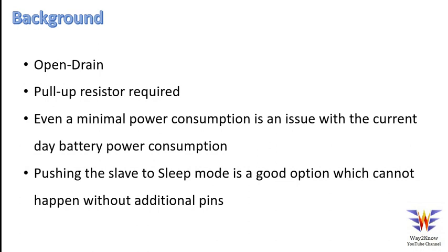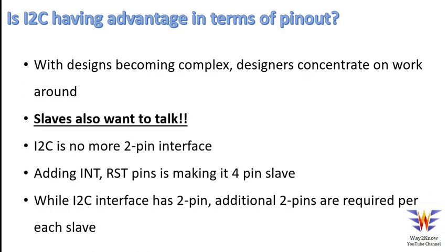And then one more important point here is, if a user has an option such that you can keep the slave in sleep mode for some time and then use it as required, then definitely it cannot happen without any additional pins. So either the power should be off, or any additional circuitry needs to be designed. So definitely that's not an option in the current scenario.